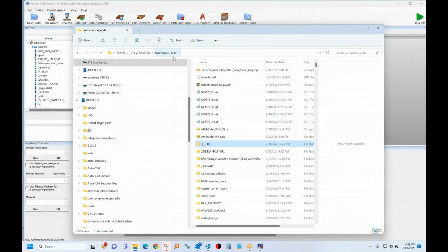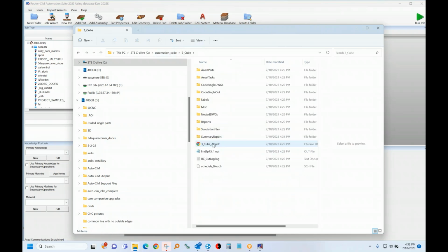And all of that came from just 2 clicks, one inside Inventor and then one on the cut list. We got 6 individual programs, 1 nested sheet program, all the parts programmed and ready to run. That is the Router Sim software with AutoNest, Solid Sim, and advanced nesting as well.